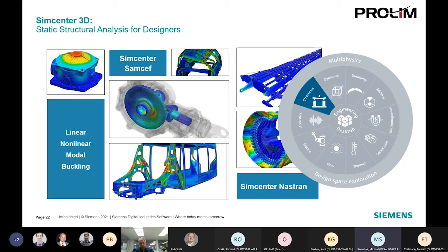Also, things like the modal analysis, where you might be looking at, in the upper left there, that casing, and seeing what's the normal mode of vibration of that part. How would that interact if we had a motor on there? Would that be an additive where both frequencies would add together and actually start to cause damage to your structure? Also, those modal analysis results can be driven into a multi-physics simulation for the dynamic response. So we can take that to the next level.